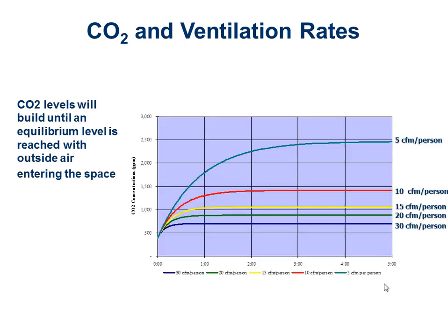I often get the question on how long is it going to take for my CO2 sensor to react. And the way I usually answer that is, well, it depends on how much you're ventilating and how many people are coming and going into the space. But basically, if we assume a bunch of people go into a room and that quantity of people stays the same, so let's say 15 of us walk into a conference room and nobody else is coming or going, we shut the door, the amount of time it takes for that space to register our CO2 levels and to level off to a neutral point is dependent on how much ventilation air I'm bringing in. If I'm only bringing in 5 CFM per person, you can see on the curve here, it's going to take 2 to 2.5 hours to get to a fairly level point. However, if I'm bringing in 10 CFM per person, it'll take about an hour.